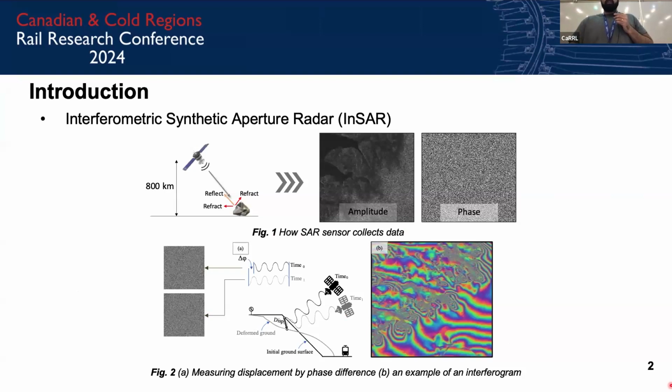The spaceborne InSAR sensor is mounted on a satellite orbiting the Earth, constantly shooting microwaves to the ground and recording the backscatters. Those backscatters can be characterized by amplitudes and phase values as any other waves. The next time the satellite is passing roughly through the same point, it makes the second acquisition. And if you subtract the phase values of these two scenes, a product called an interferogram is generated, which can later on be converted into displacement maps.